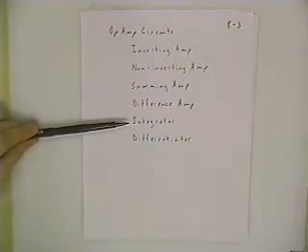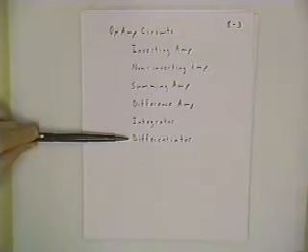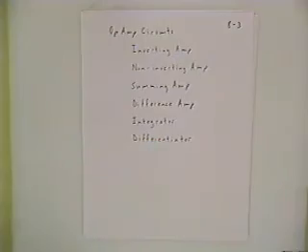For signal processing, sometimes we want to have the integral of the input signal or the derivative of the input signal, and that's where these circuits called integrator and differentiator come in. So now what I want to do is take you through a couple of examples. We have time for about 3 of these to show you how to use this ideal model to figure out some of the circuit problems involving op amps that you might see on the exam.